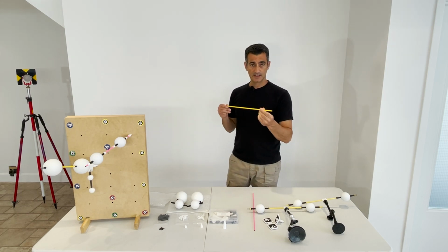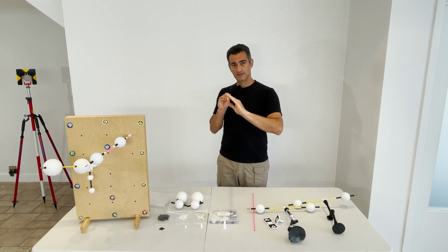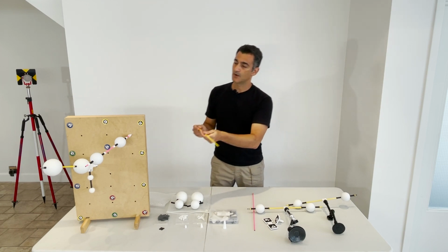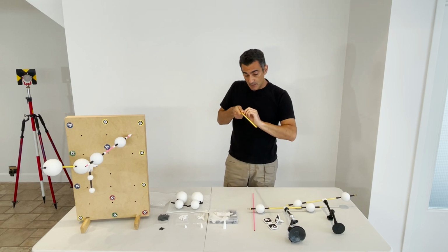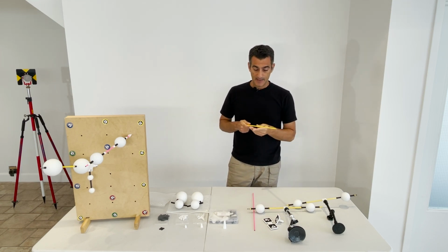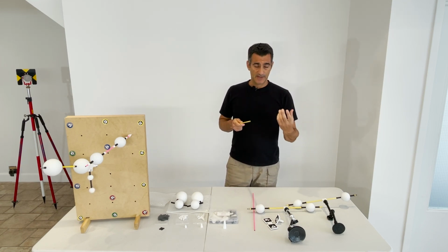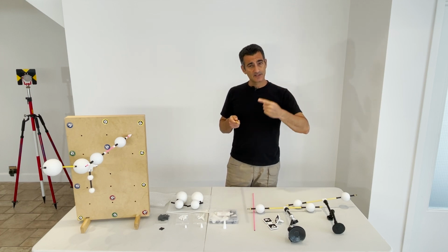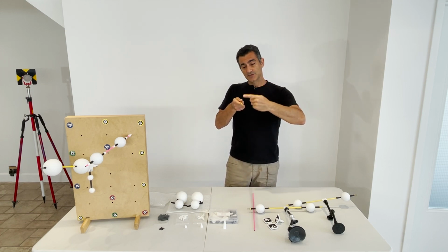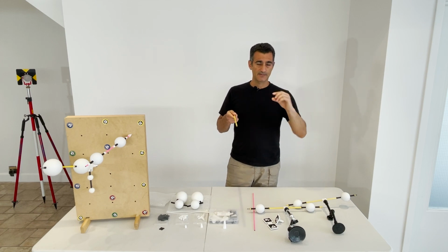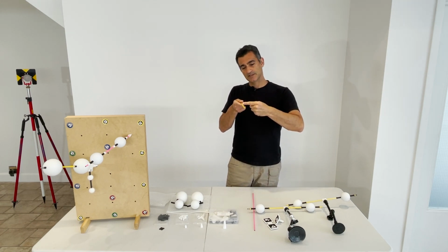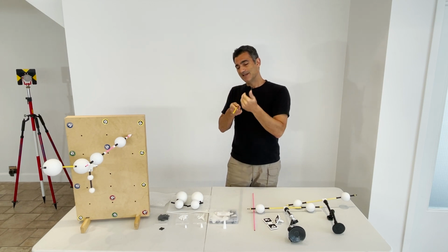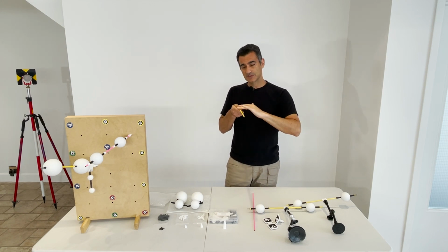One is I'm scanning and only using a rod. I'm just going to scan and hope. So I didn't have these spheres on here. I'm just going to scan this and hope that I recover points along this rod. Well, there's something called edge effects. The laser coming out of the scanner is 2 or 3 millimeters, but it has some width to it. So you run into a situation where part of the beam hits the rod and part of it misses, and there's often some confusion in the instrument as to where the surface actually is.